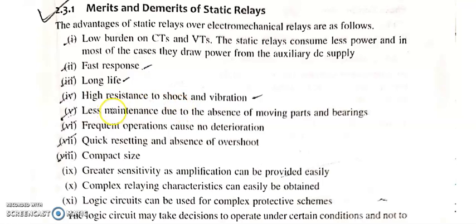Maintenance cost is less, because there are no moving parts as well as bearings, just like in an electromechanical relay, where you found disc, bearings, ball bearings, spindle, either cup or disc type. But here there are no such things, so maintenance is minimal. You can't say zero maintenance, but you can say less maintenance. So frequent operations we can perform without any deterioration.